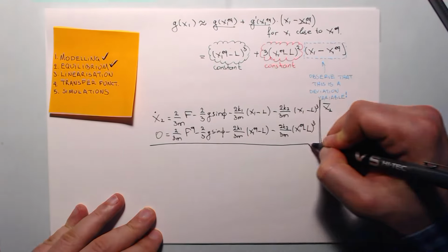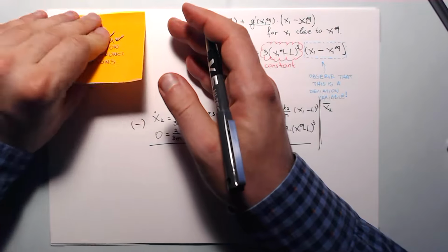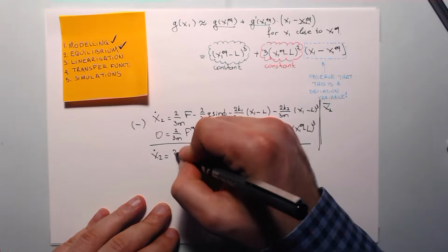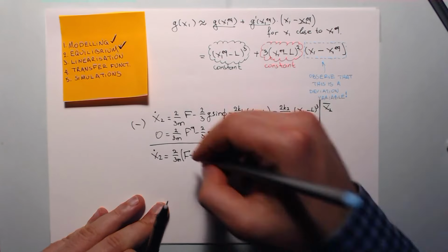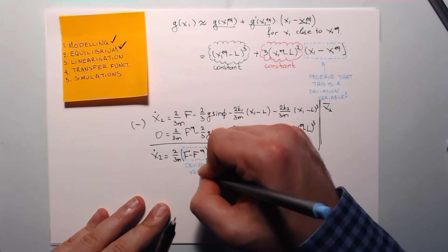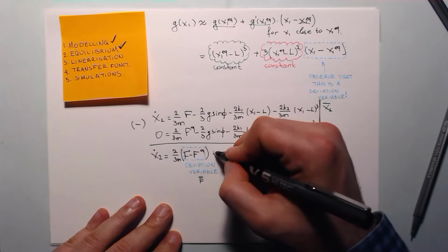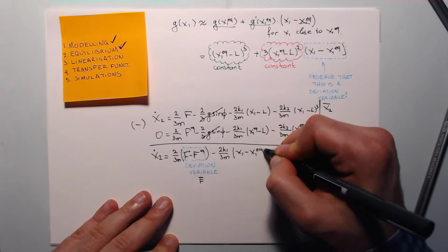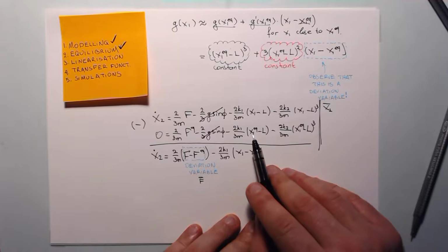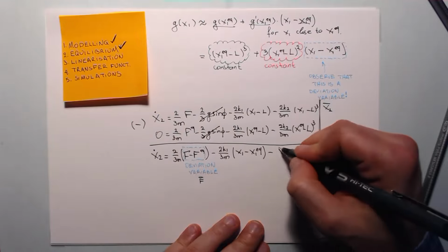Now draw a line here, take a subtraction, subtract the two equations by part, f minus f equilibrium, and again, if you're very observant, you will observe that this is again a deviation variable. It is the one we call f bar. These constants will be eliminated. Now this is x1 minus x1 EQ, and the L's are also eliminated.